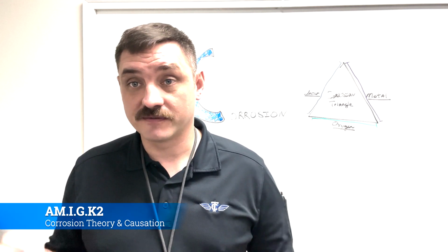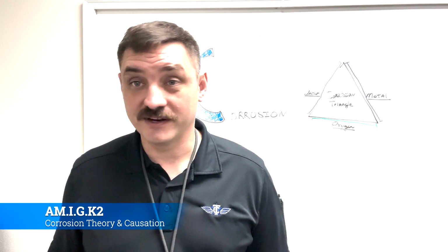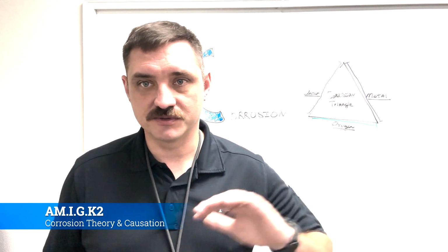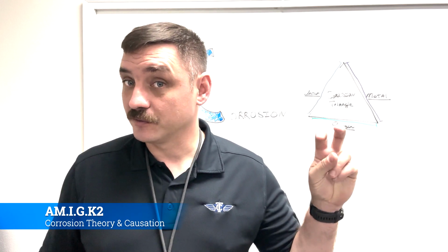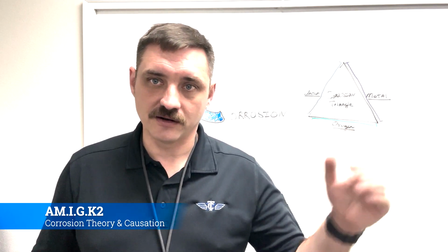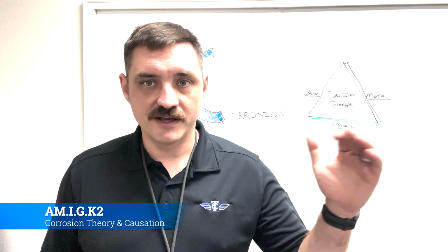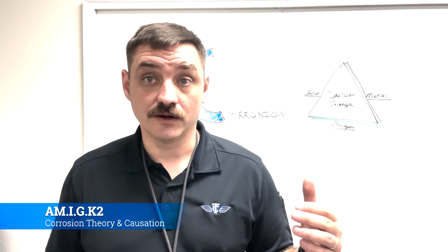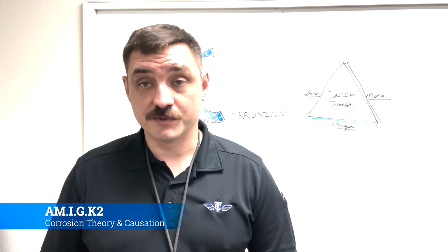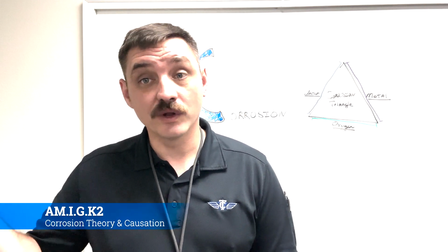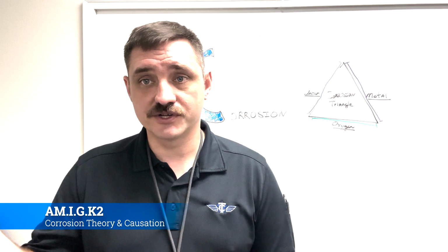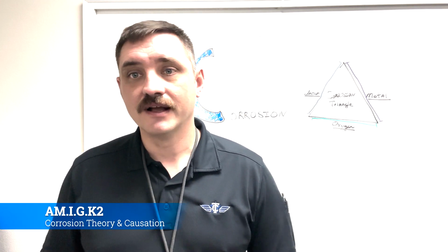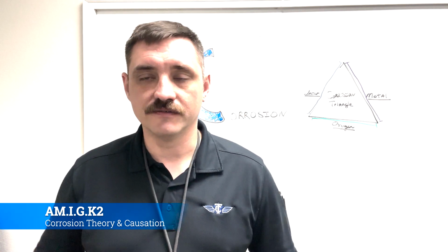The problem is that whenever that sulfuric acid gets on the airplane, it just eats the airplane up. What's happening there is a chemical exchange between dissimilar materials, in this case an acid and a metal. It's going to eat the paint away, then start reacting with the metal, and that's going to create rampant corrosion. There's been more than one airplane I've seen with old lead acid batteries that somebody turned too hard, or did some kind of thing they weren't supposed to do, the battery came loose, battery acid goes everywhere, and then it just eats the whole back end of the airplane up.